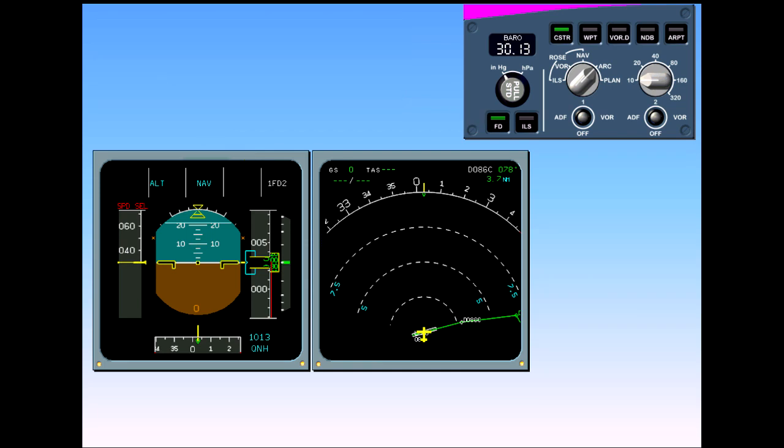Notice that there are no Flight Director crossbars displayed. This is normal because on the ground they are not required. You will see later that during the takeoff, the Flight Director command bars will automatically appear. You will learn more on Flight Directors in the Autoflight modules.